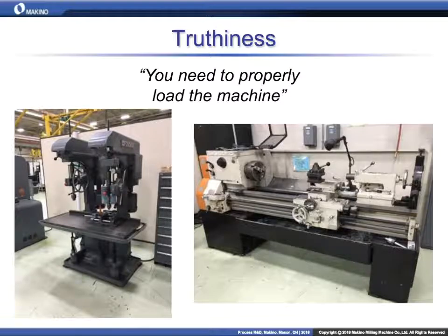But I think it came from the manual machining days, saying, for this particular lathe here, there's nothing holding the bed or the slide down except gravity. So you always want the cutting forces that you generate while turning to be in the down direction. Yeah. So you're always pushing the slide onto the table. Right. So maybe that's where it came from.